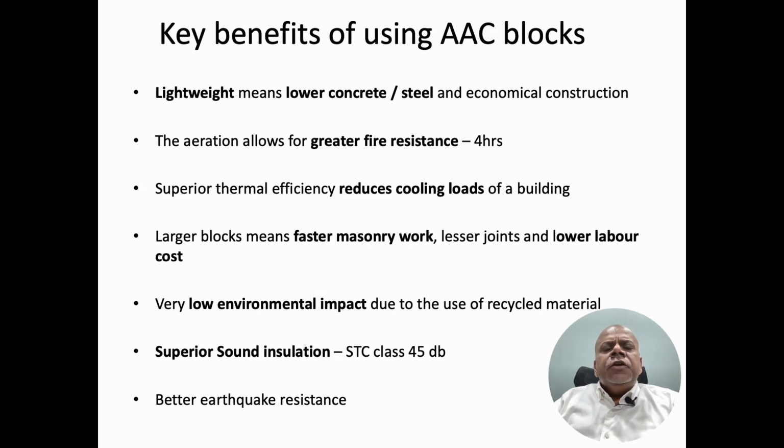So friends, let's look at the key benefits which I have already discussed with you. Lightweight, lower concrete and steel. Aeration, more fire resistance. Superior thermal efficiency, reduces the cooling load of a building. Imagine I am sitting in this room and I need a 2-ton air conditioner to cool down. But if the same room is done with AAC, instead of clay bricks, you can do the job in 1.5 tons of air conditioning. So there is lifelong saving in your air conditioning cost.